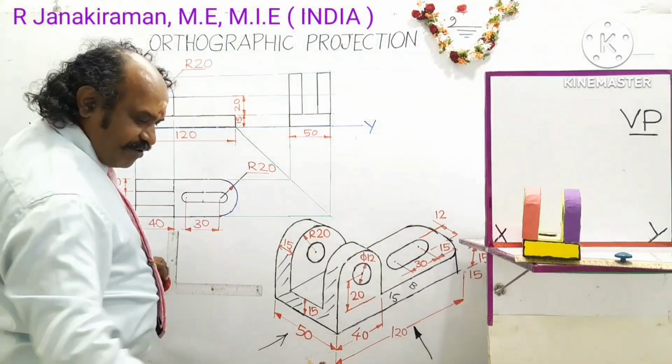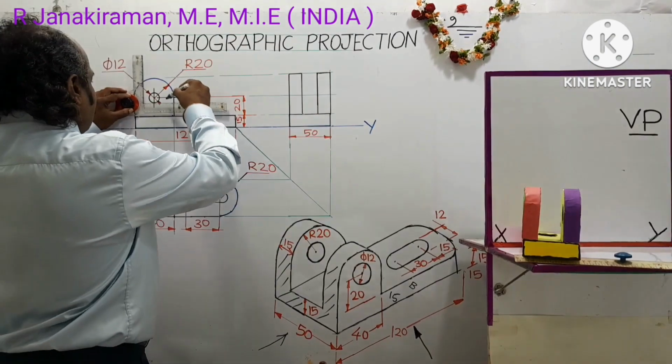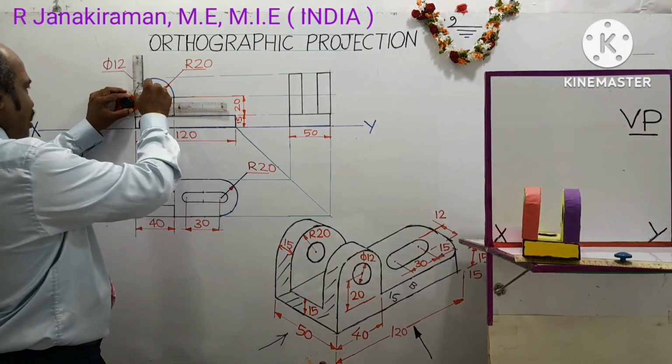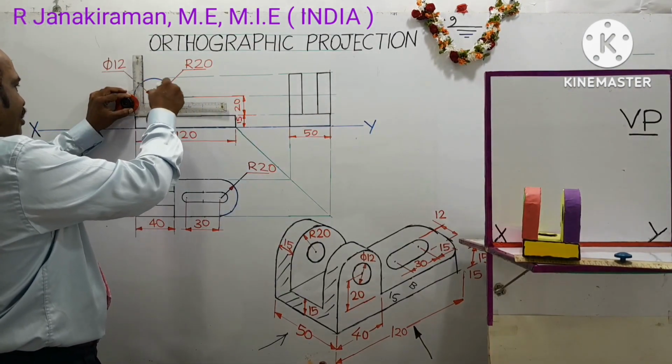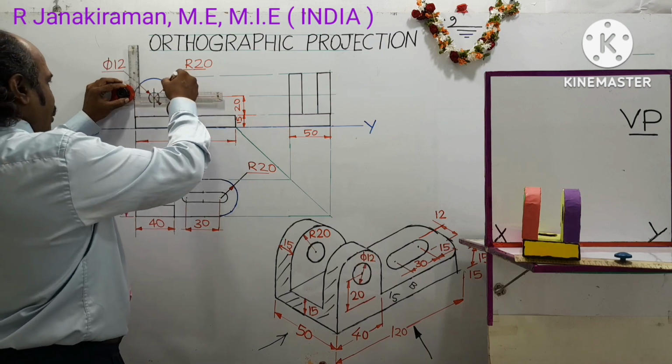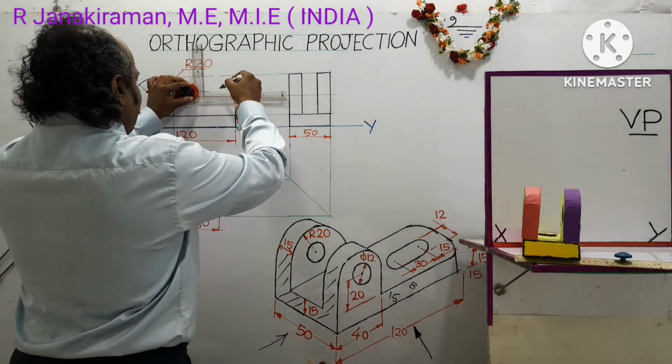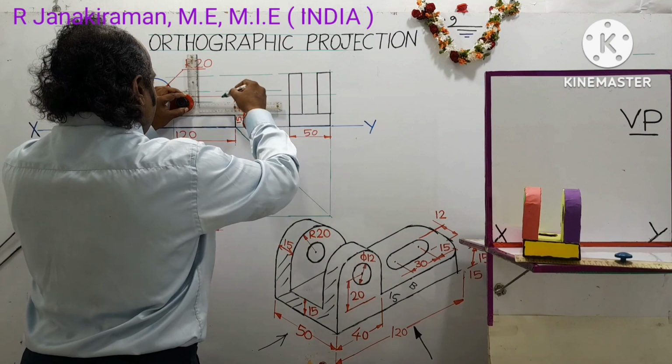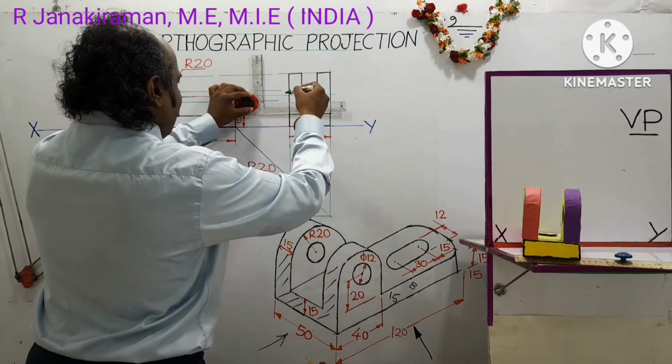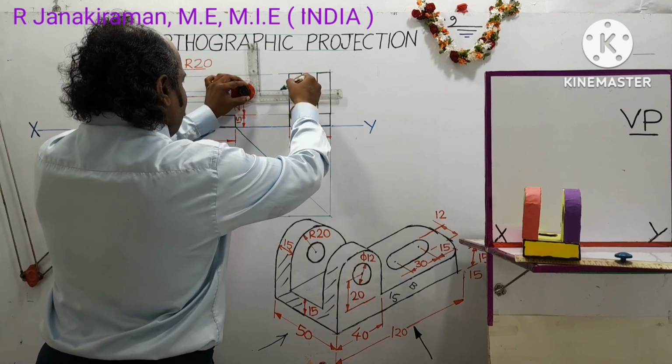Okay, from the previous front view, draw a horizontal projector from here to here, which will be the diameter of the circle. Draw a horizontal projector where it intersects with the side view. There you draw a dashed line using an HB pencil. Here and here it intersects.